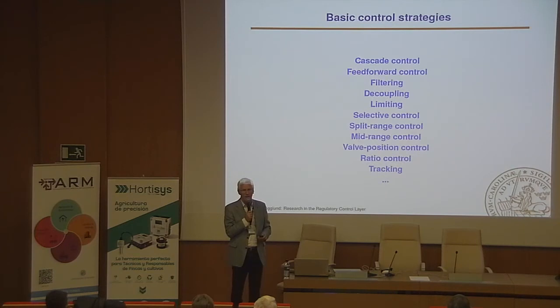On the other hand, I'm not that experienced in MPC, but my impression is that it's a very complicated framework. I talked about this ratio controller in a Nordic meeting a month ago, and there were people from former Statoil, now Borealis, and they're really, really good at MPC, and they claim that no, we would like to have ratio controllers at the bottom. We don't want to solve those problems in the MPC. We would like to have them solved in the regulatory control layer. So, it depends on who you ask.